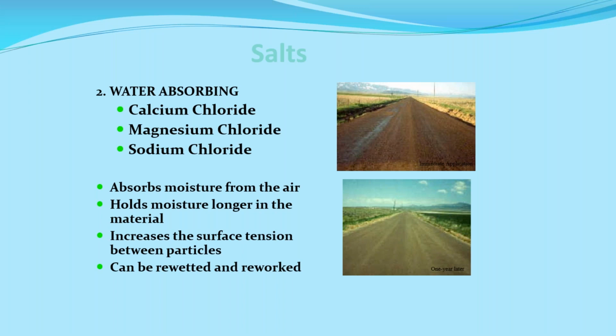Some agencies like to grade the gravel roadway or the unpaved roadway, have the material all fluffed up, and then apply their chemical on it and then compact it. If you do that, or if you run your grader through that calcium chloride, magnesium chloride, or sodium chloride, you need to wash the material off of your piece of equipment. Otherwise, it will rust. It will cause you problems.